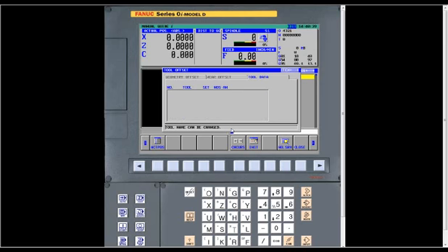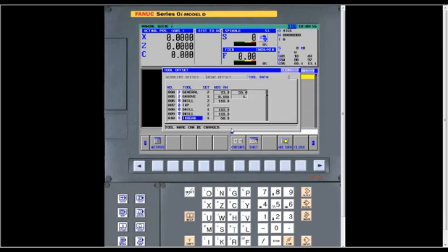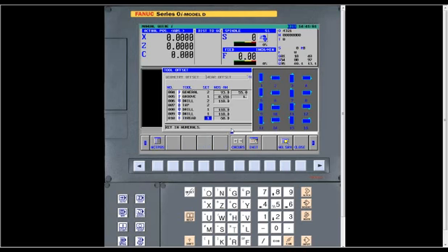In a tap, you don't have to put a lot of information, just the tool type has to be correct, and then the orientation. On a horizontal lathe, it's typically going to be a number 2 for the left spindle. Then for threading, you don't have to put a lot of information, just the right tool type. Again, the setting based on what your tool looks like, and then the angle on your insert.